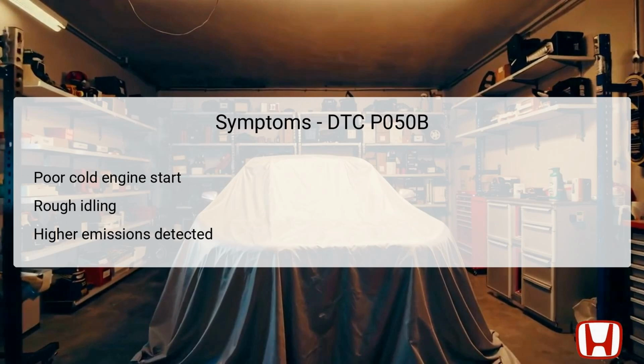Common symptoms associated with DTC P050B primarily revolve around engine performance during cold starts. A poor cold engine start indicates that the ignition timing may be off, preventing the engine from starting smoothly. Rough idling can also manifest if the engine does eventually start. This occurs when the ignition timing does not adequately adjust for the cooler engine temperature. Additionally, higher emissions could be a symptom,